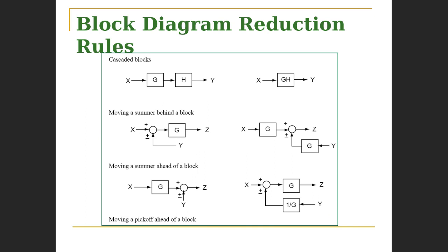So let's get into the procedure of moving this summing node. Now, to better appreciate what is happening, there are two signals going into the block G. And let us take, first of all, the possibility of a plus and plus node. All right, so I'm going to try and put a mark over the negative. That's what we're looking at right now, plus and plus.